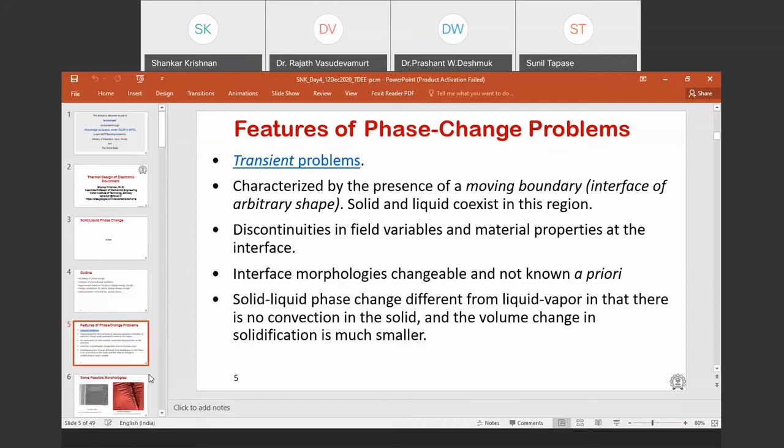Once the melting is complete, it will go to a steady state where the heatsink is able to handle that power. During that period, the melted material will re-solidify and will be ready to take up the next starting period. So that's the idea behind this phase change material. And I will show another example as well.